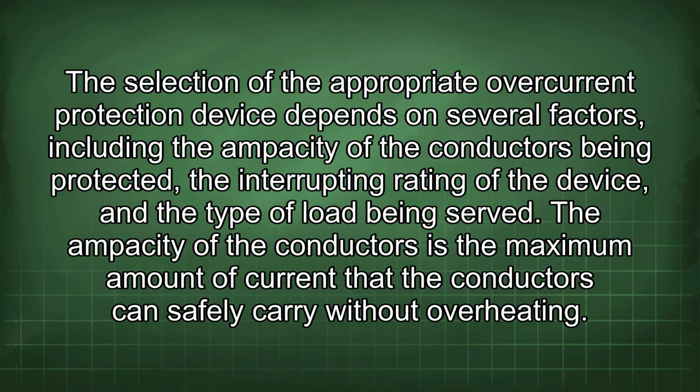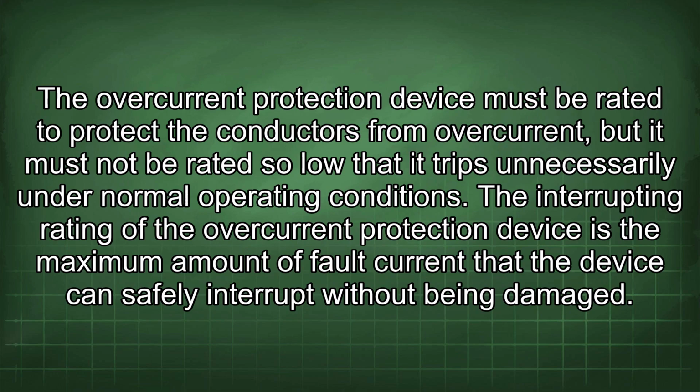The selection of the appropriate overcurrent protection device depends on several factors, including the ampacity of the conductors being protected, the interrupting rating of the device, and the type of load being served. The ampacity of the conductors is the maximum amount of current that the conductors can safely carry without overheating. The overcurrent protection device must be rated to protect the conductors from overcurrent, but it must not be rated so low that it trips unnecessarily under normal operating conditions.